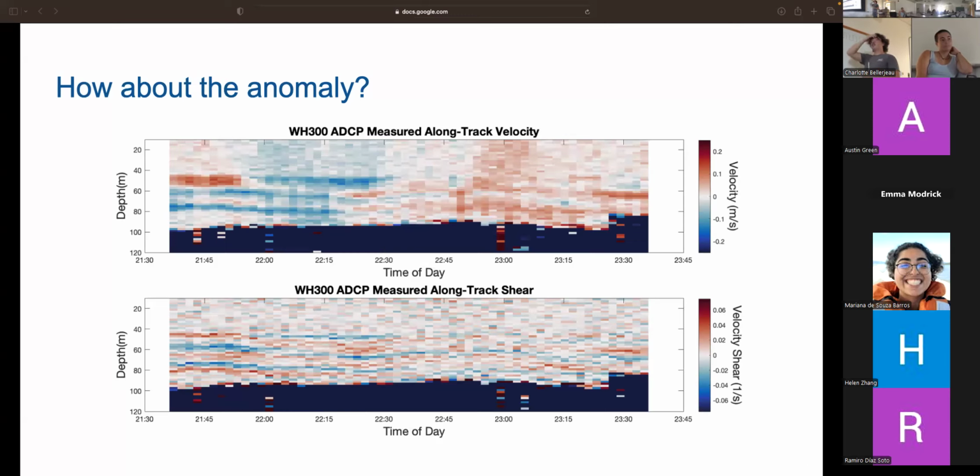It depends on the configuration of the ADCP, to know where you need to cut. When we get these measurements, we get an intensity of the return itself, coherence, and a velocity measurement as well. So we usually cut off based on the intensity. If you plot it, which I can pull up from some other work we've done, you'll see a normal, regular intensity value, and then up here it will be orders of magnitude higher. That's how you know you're getting some weird side lobe from the machine. Okay, thank you.